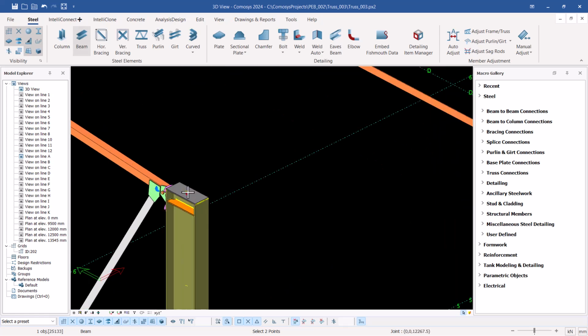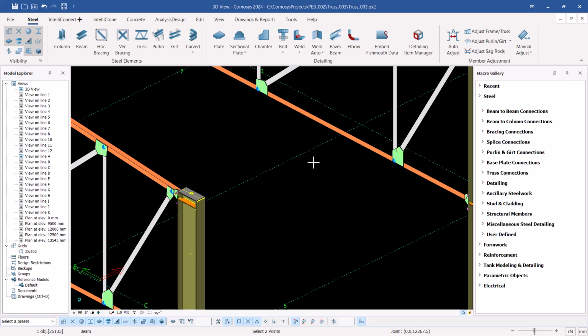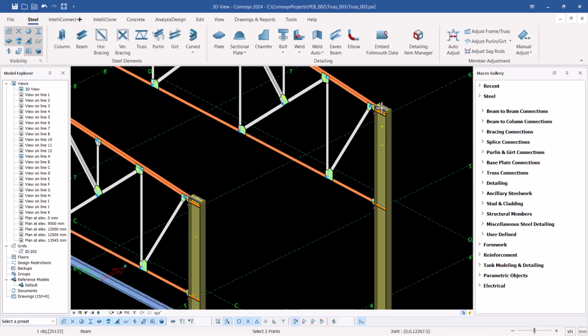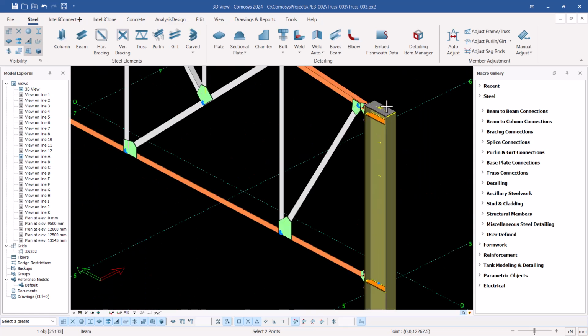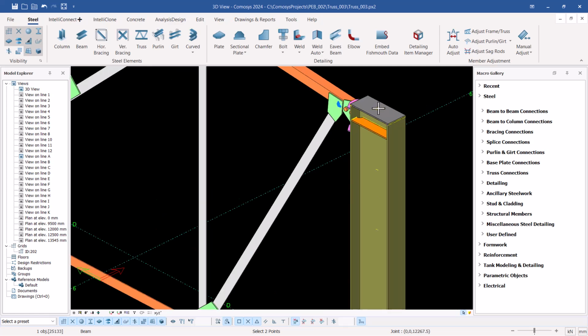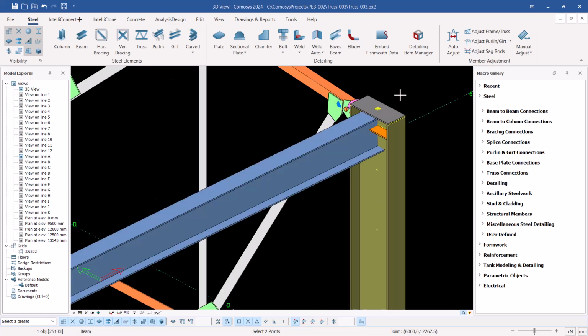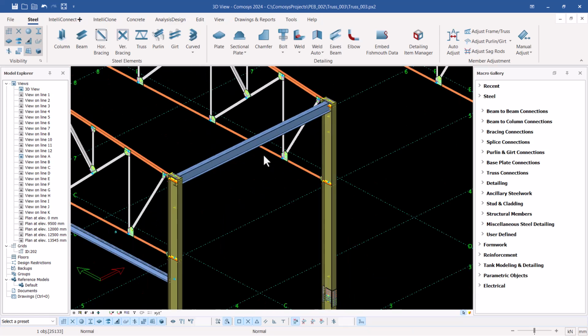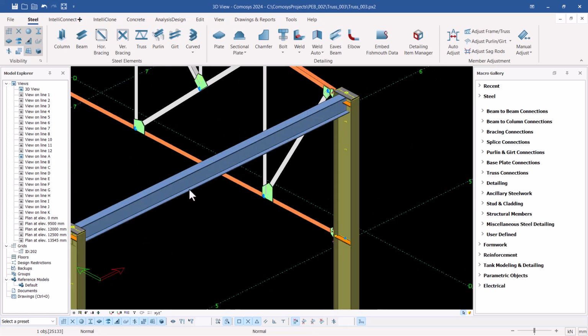So let me just snap on top there and snap on the other end there. Let me just bring this close so that I'll be able to snap on accurate position right there. So let me just snap right there. Then right click and click interrupt to just get off that command, and I want to give it an offset downward by maybe 400, 500.